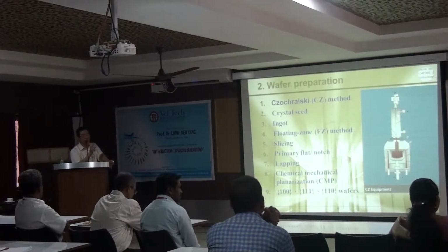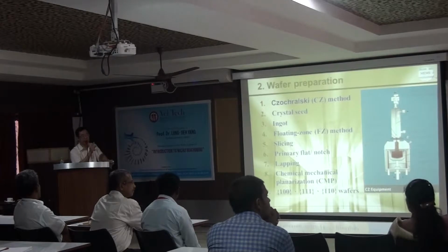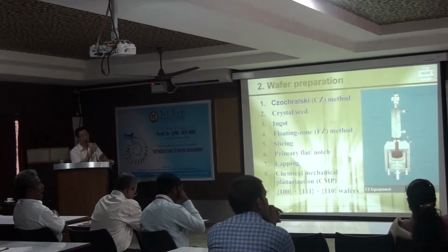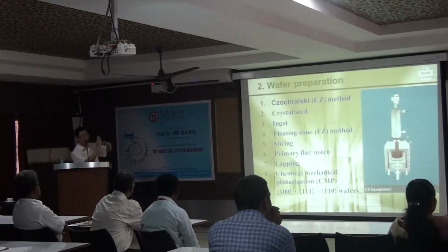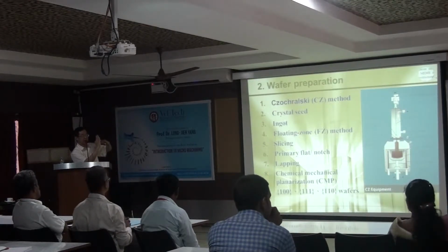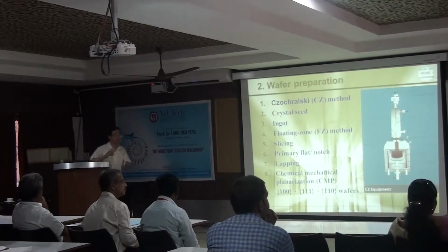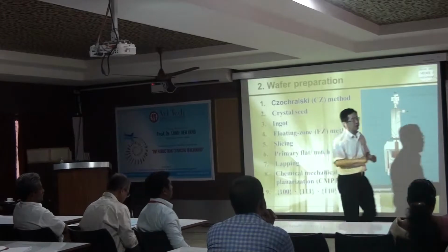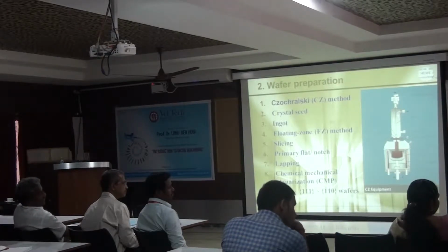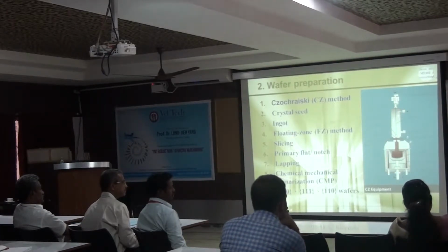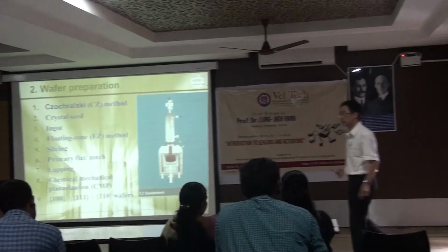So we follow the tradition of cutting. We identify the primary flat on the wafer, and for all the directions or layout of our semiconductor devices, we always do the alignment along the primary flat direction. Finally, this single crystal wafer will be divided into many chips, with all these scribe lines along the 110 direction.